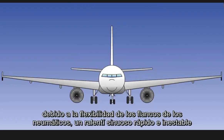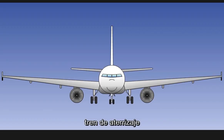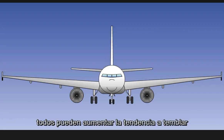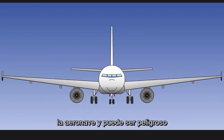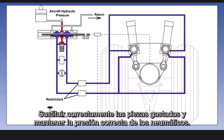Due to the flexibility of tyre sidewalls, an unstable, rapid, sinusoidal oscillation or vibration, known as shimmy, can be induced into the nose undercarriage. Worn or broken torque links, wear in the wheel bearings, and uneven tyre pressures can all increase the tendency to shimmy. Excessive shimmy, especially at high speeds, can set up vibrations throughout the aircraft and can be dangerous. The best ways to keep shimmy to a minimum are to maintain the nose gear correctly, replacing worn-out parts, and by maintaining correct tyre pressures.